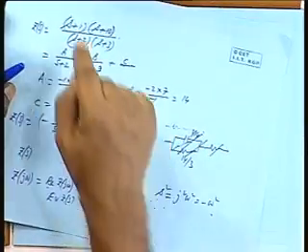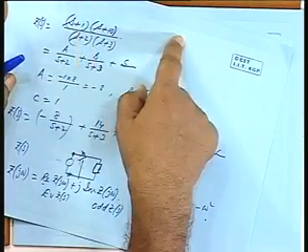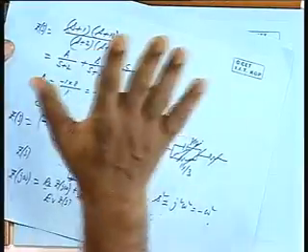So if you find that this test fails, it is not positive throughout for all values of omega, somewhere it is becoming negative, then you can say it is not realizable by passive elements. This is not a network function. Is that alright? So we will stop here for today. We will continue with this and a few simple realizations we will see with LC, RC and so on.